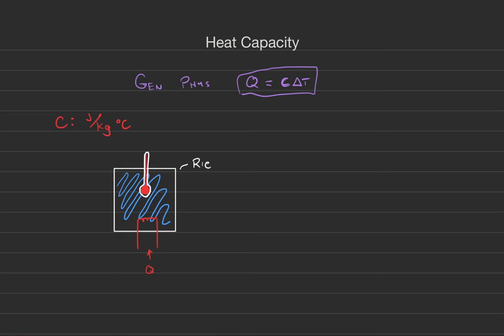So we got a rigid vessel, and therefore volume is constant. So what we call this situation is that it's under a constant volume. We have heat going in, and it's going to raise that temperature until it raises it 1 degree. And when it does that, we have what's called the constant volume heat capacity.